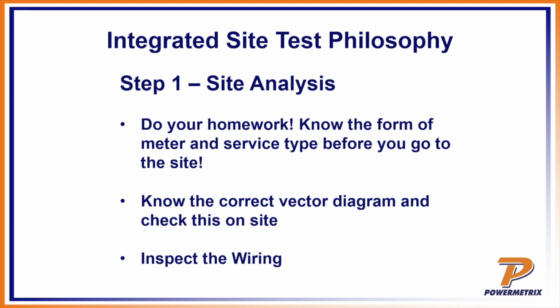So the first part is the site analysis. In the site analysis, you want to do your homework. You want to know what it is you're testing, what form would I expect, what service type before I go into the site. I want to know the correct vector diagram and to be able to check it on the site and to know what kind of wiring to expect.